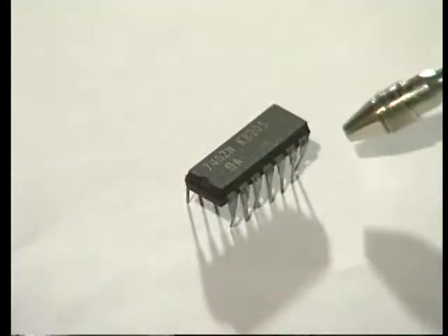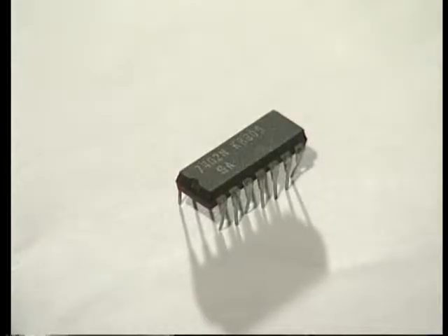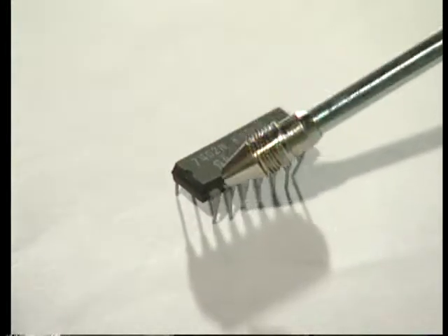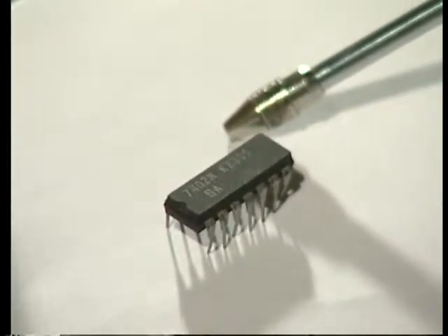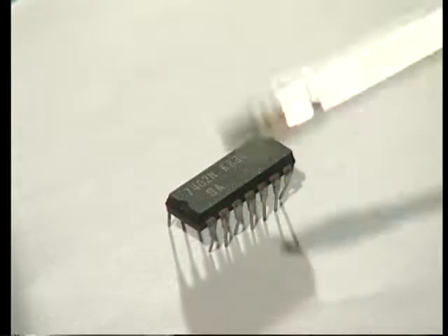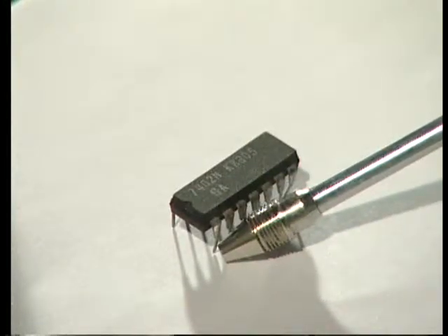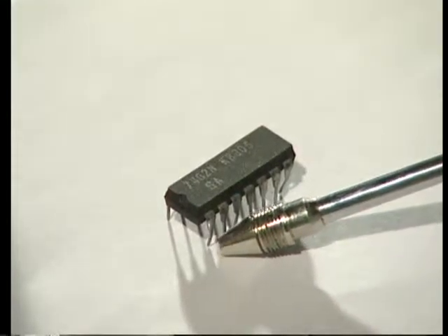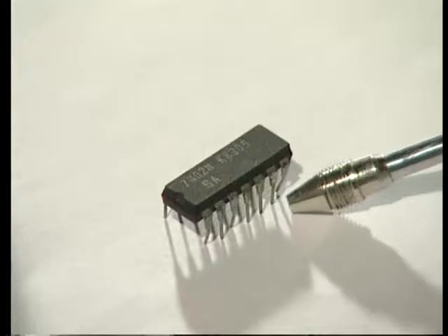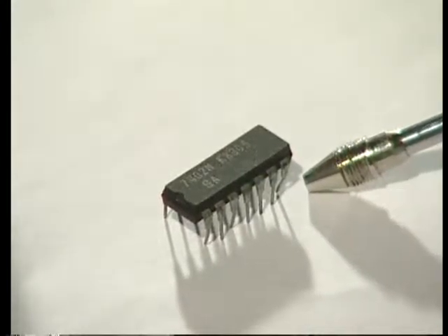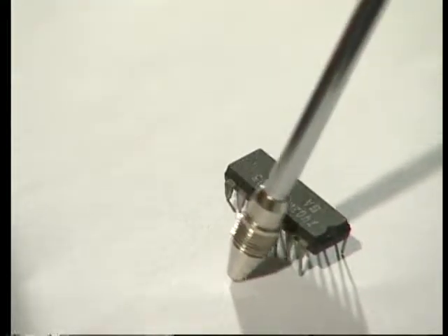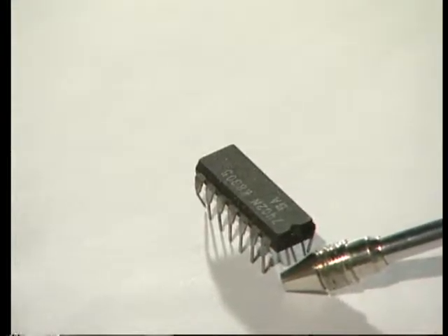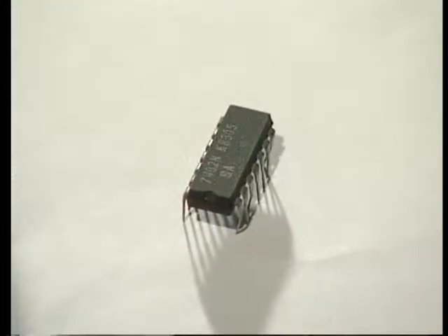You can see the 7402. This is also on the same lines as that of 7400. You can see a notch over here. You can observe that there are 14 pins. So, starting from the left side of the notch, keeping the notch to the top and observing from the top left side, this is pin number 1. Then coming downwards, we move up to pin number 7, then pin number 8 and move to the top towards pin number 14. This will be VCC. This is a quad 2 input NOR gate.